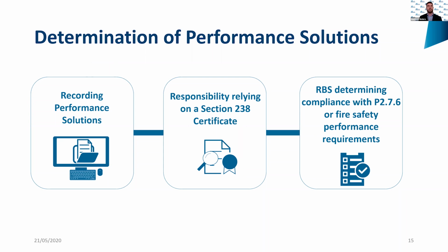Now, this includes code mark certificates. We had a lot of questions yesterday around if you still need to list a code mark certificate. It's only in situations where they're used as evidence of suitability for a performance solution. So if they're used for a deemed to satisfy solution, you don't list it. You'd only list it for a performance solution. So we had a lot of questions around code mark, and we'll go through some examples a little bit later, so we'll certainly touch on that.